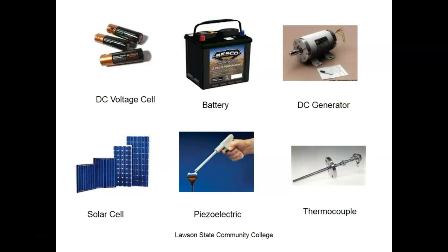So these are some of the devices. We have voltage cells. Most people call them batteries. It's incorrect, but that's the commercial name for them now, because everybody doesn't know that a battery means more than one, right? So a car battery is a true battery. All these A cells, AA, AAA, were technically cells, but everybody calls them batteries. Now a 9-volt is a battery. If you ever tore a 9-volt apart, you'd see 6 cells in there, 1.5 volts per cell, 9 volts.